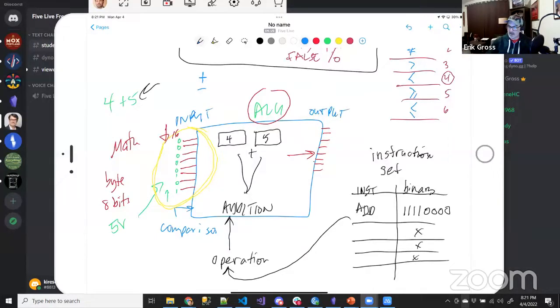And so it being 9, it puts another pattern on here. It says, hey, CPU, ignore those output wires. I'm not done yet. All right, let me set it all up. All right, so that's a 9, which means I need a 1, 0, 0, 1, 0, 0, 0, 0. Okay, I got that all set up. Hey, CPU, go ahead and read these wires, please. I have your answer. And the CPU goes, oh, look at that pattern. That pattern is 0, 0, 0, 0, 1, 0, 0, 1. I'm going to take that and use it wherever it's needed.